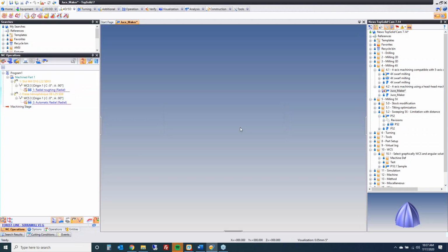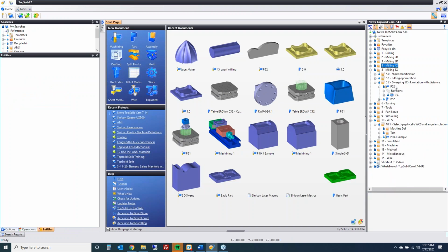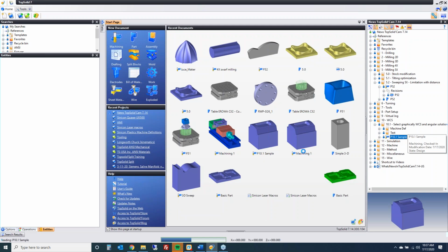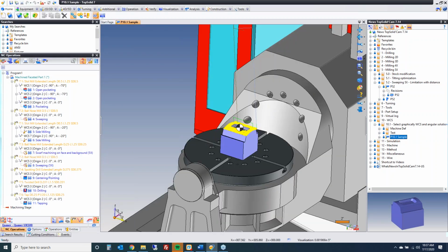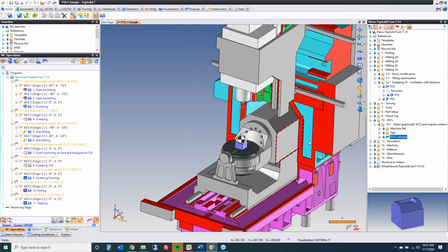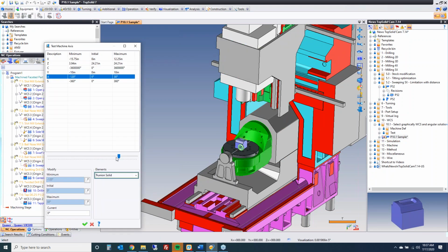So let's move on to 5-axis. Now, before I get into 5-axis continuous stuff, I want to talk about a new improvement to managing WCSs. So this one I think is really, really interesting. Here we're on a 5-axis quasar machine. Let's go look at the kinematics just so we all get familiar with it. The tilt axis, we can tilt that far that way, only that far that way. So there's definitely some rotary limits.